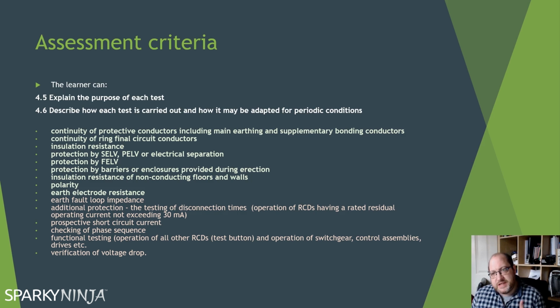If we have a TNCS system, though, we do need to remember that whilst the TNCS system uses the neutral as a return path, and so saying it's a prospective short circuit current will give us the equivalent, if we have parallels, water systems, gas systems, structural framework, then potentially the prospective earth fault current may be higher than the prospective short circuit current on a single phase system, because you'll have the parallels supporting the lowered resistance of the earth fault, whilst with the short circuit you won't.